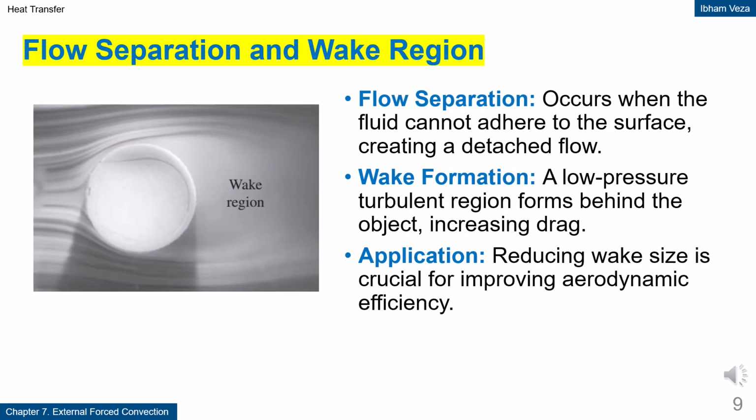Flow separation and wake region. This slide introduces the phenomenon of flow separation when the fluid can no longer follow the surface contour. As a result, a wake region with low pressure and turbulent flow is formed behind the object. This wake region contributes significantly to pressure drag. The larger the wake, the larger the drag force. Therefore, many aerodynamic designs focus on reducing the wake size.